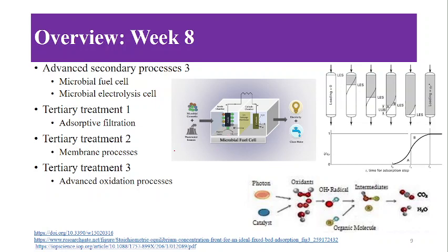And one more tertiary treatment process is the advanced oxidation process, which uses hydroxyl radicals, an oxidant which oxidizes the contaminants present in the wastewater, so that we can remove these pollutants from the wastewater.